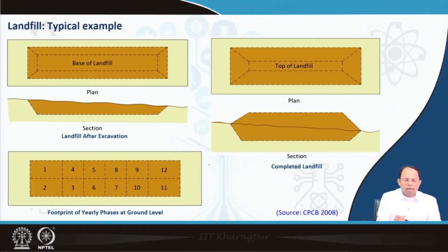Now let us assume this is the section of the landfill, the profile of the ground. We can go a little bit below, maybe groundwater is available even below, so we maintain the minimum distance, and we can dig up and go for a trench fill initially, and then as we have discussed earlier, most landfills are like a modified area landfill. So over here you can see that eventually the landfill will look like this, some part below, some part above.